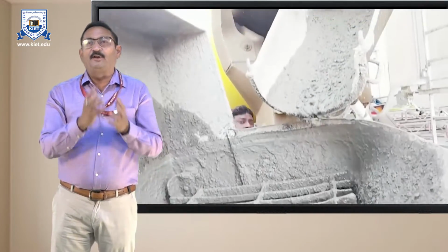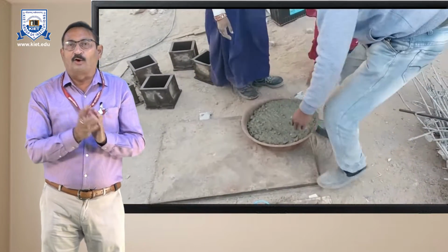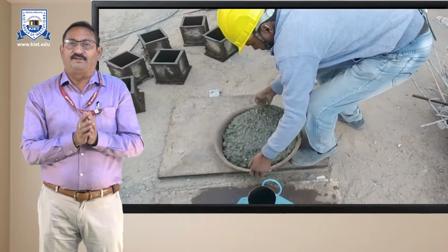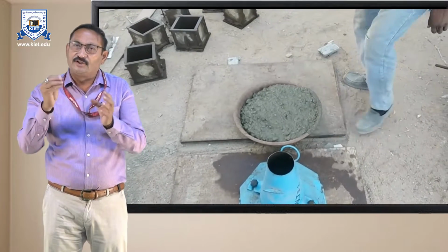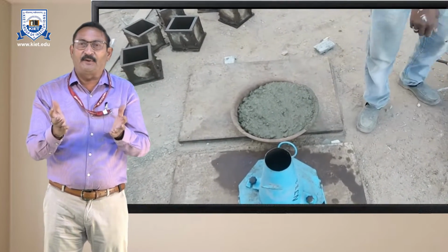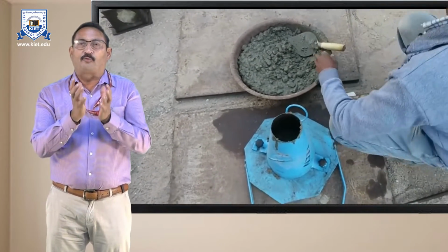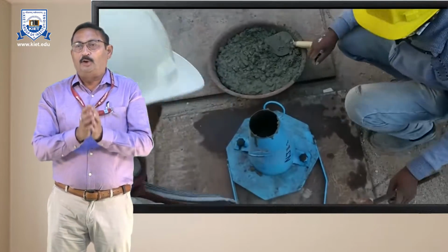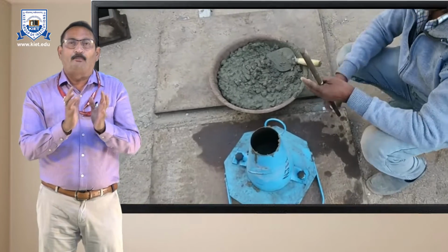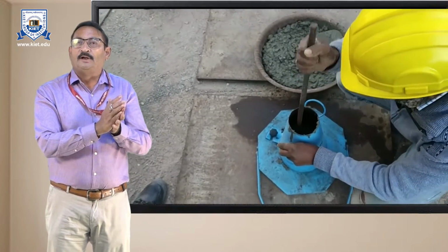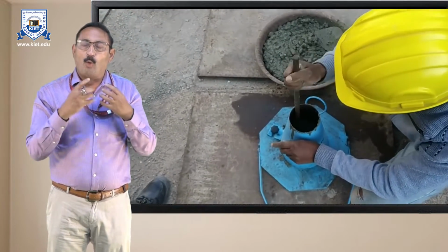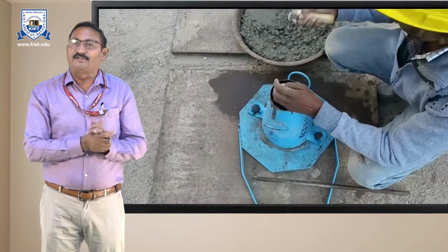Essentially, the permeability of concrete is governed by the quality and continuity of the paste, since little water flows through aggregate either under pressure or by capillarity. Since the properties of concrete are governed to a considerable extent by the quality of paste, it is helpful to consider more closely the structure of the paste.